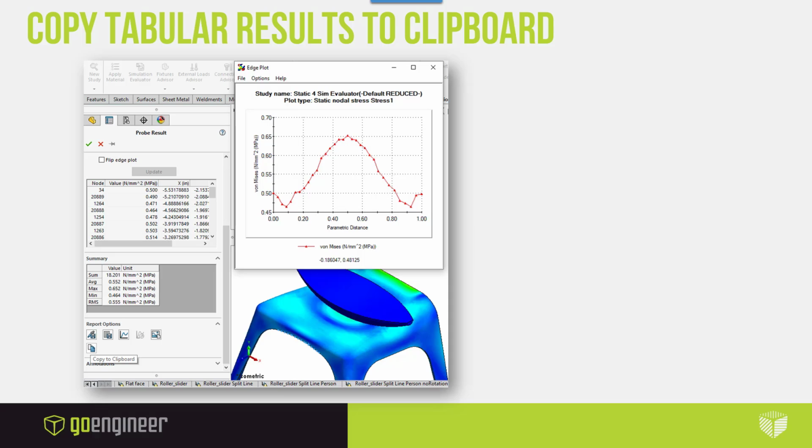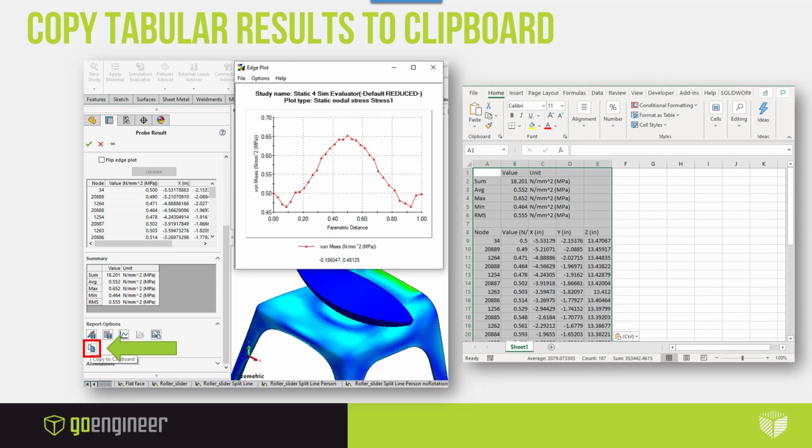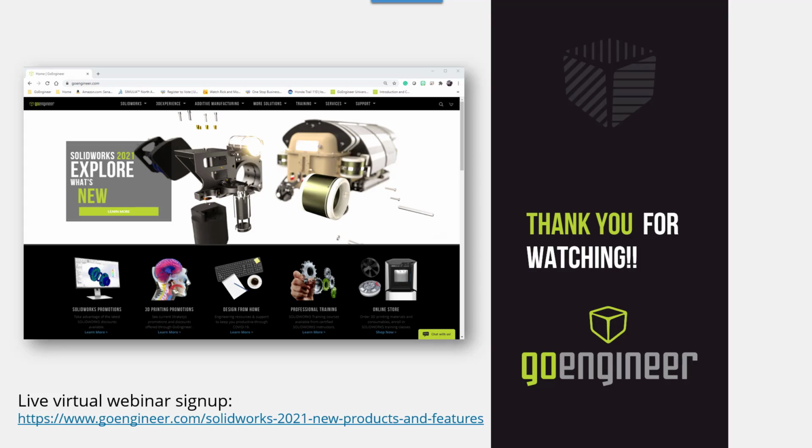And then last, we now have the ability to copy the results that you actually get in the plot. So when you are in the probe property manager or the list forces manager, you now have the option to copy to clipboard. So now you'll be able to copy all of this data and then bring it into whatever spreadsheet application you are going to use to post-process that data a bit more. That's just about it for the Simulation 2021 content that we have.